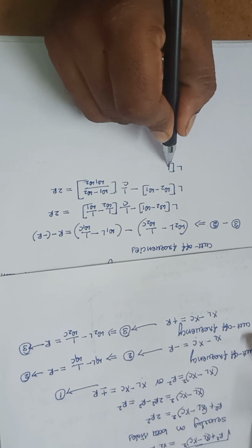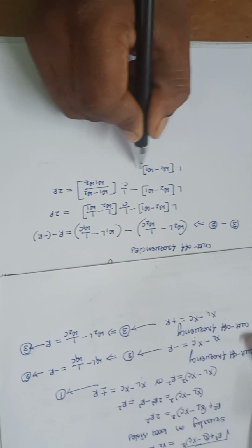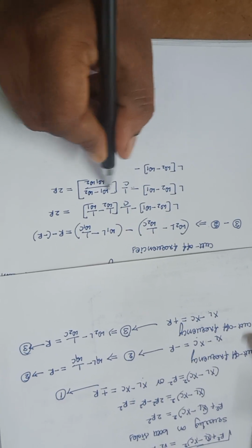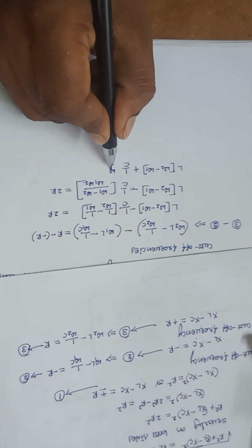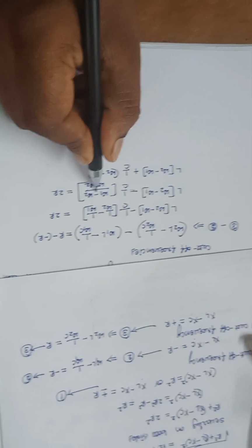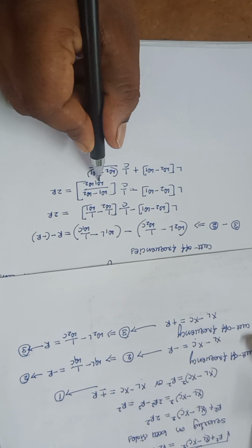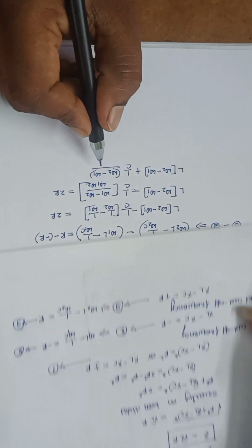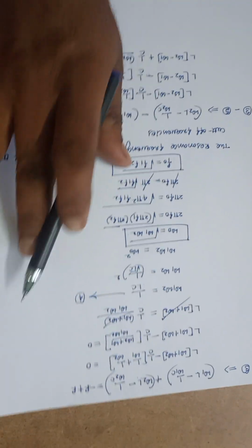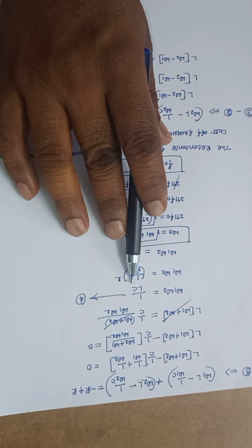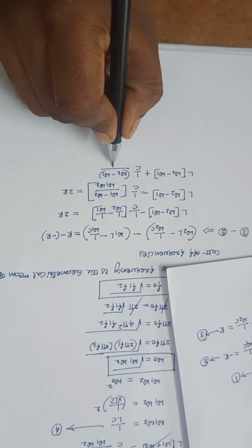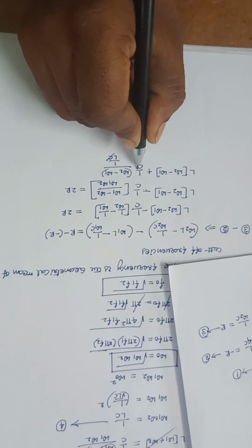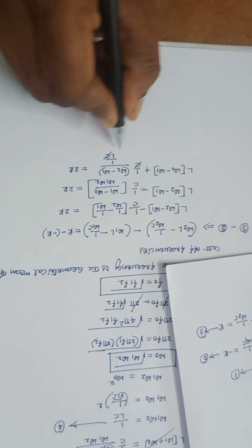Now L into omega 2 minus omega 1. Just crossing the minus, I can write it as 1 by C into omega 2 minus omega 1, taking the minus as common here. So instead of omega 1 omega 2, from equation number 4, omega 1 into omega 2 is 1 by LC. I am substituting this 1 by LC. This C and this C will get cancelled.